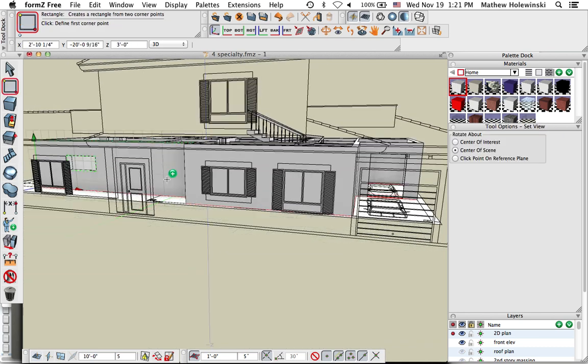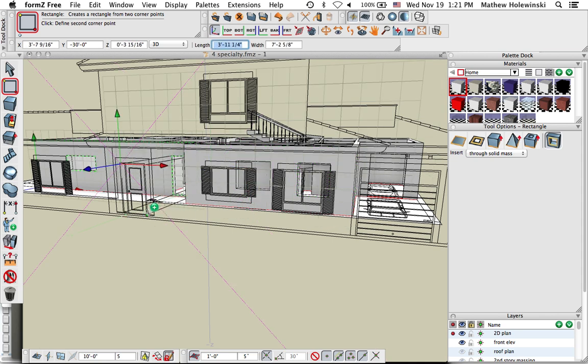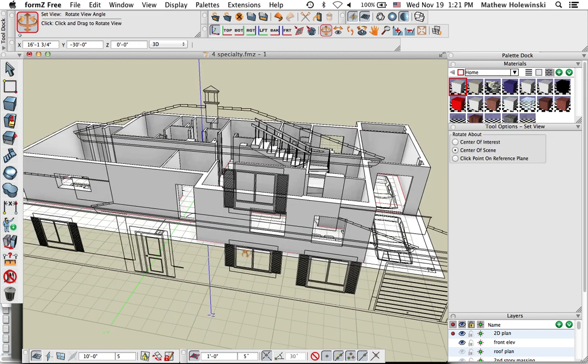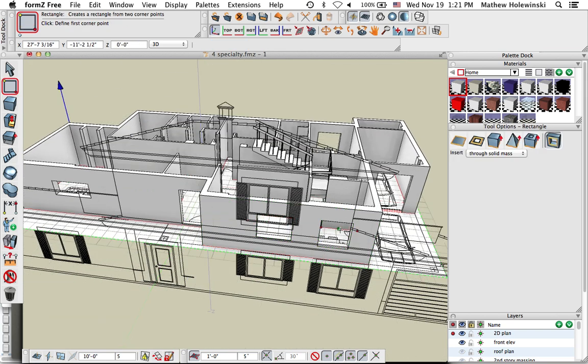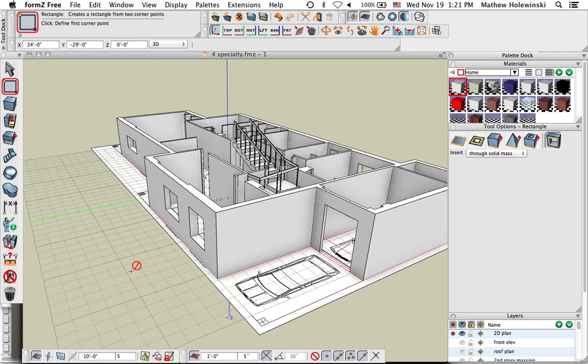and you can see that when I'm using the drawing tool with the insert opening option, I can just snap to the actual positions on that front elevation, and you can see that it orthographically projects into that first face that we're actually drawing on. You can see that those holes have now been accurately positioned in the front of that object. Okay, so that's just another way of doing that.